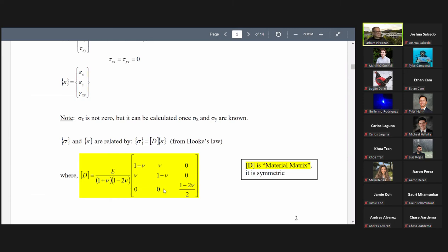But some materials like elastomers, and some of these new materials, may behave in a way that we have to be more cautious about. Sometimes even Poisson's ratio can be negative. Some materials, when you stretch them in the x direction, also expand in the y direction. These are very rare cases, like foam, for example. It is very unusual, but these are very special cases we have to pay attention to.